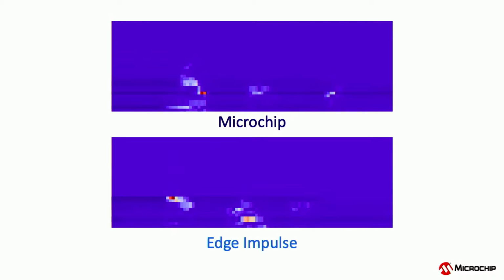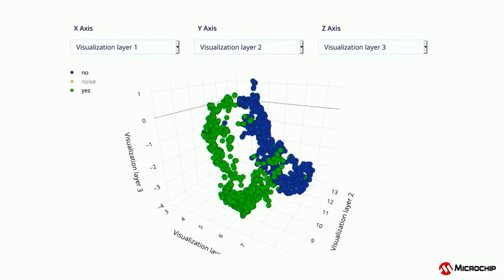But then we do a whole bunch of fast Fourier transforms over this data and build a spectrogram, and here it's optimized for human speech. Then already I can distinguish between these 2 things very quickly. So this is data, no machine learning involved in the slide that you see here. This is just data from a keyword spotting data set, so raw audio data. We've put that through a Mel frequency cepstral coefficient feature extraction block, so a bunch of FFTs, and normalization.